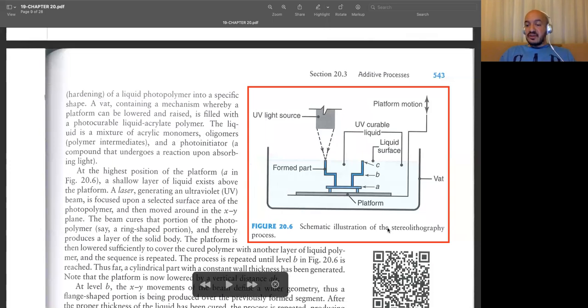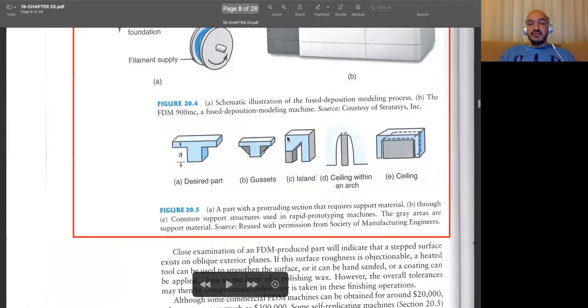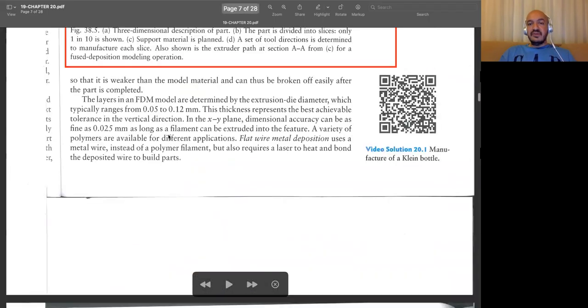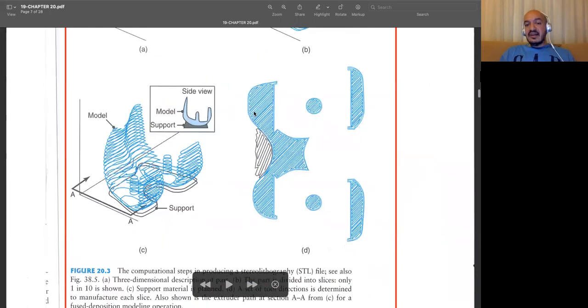And in stereolithography systems, we make use of this main principle of photopolymerization. And what about the rest? How do we manufacture complicated products? At the beginning of the process, the platform is at the top of this vat. So we have little liquid material at the top, and then our light source moves, as in the case of FDM technology.